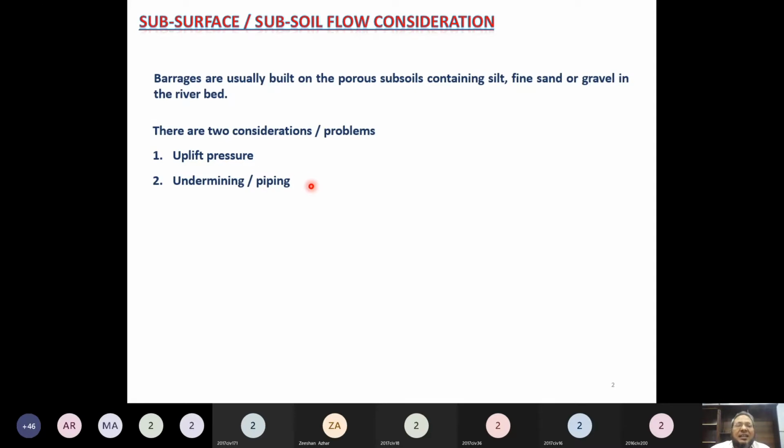What is the second problem created by this subsurface flow under the barrage? There is undermining and piping. When the water has to flow in the soil, then at the exit point from where the water will have to emerge, while water is flowing, it applies seepage force on the soil particles.